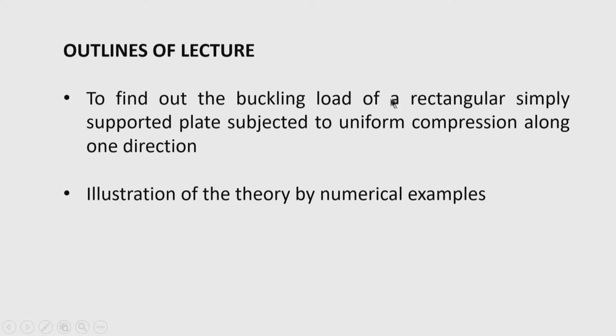Although the illustration is done with a uniform compression, the general formulation that I have derived in the earlier class can be used to solve a problem of rectangular plate with biaxial compression as well as the shear loading, membrane shear loading.